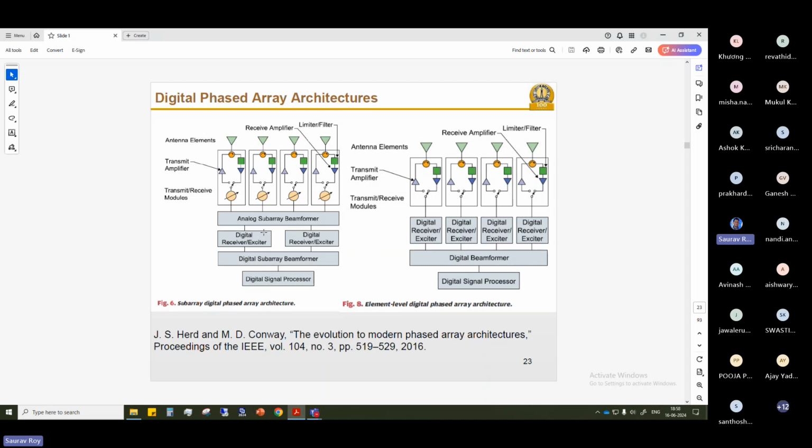See, I and Q, these two signals, are baseband. Whatever we generate from your computer or microcontroller, this data I and Q that you provide gets multiplied with your carrier signal, and then it's added up and transmitted through the antenna. That is what happens.